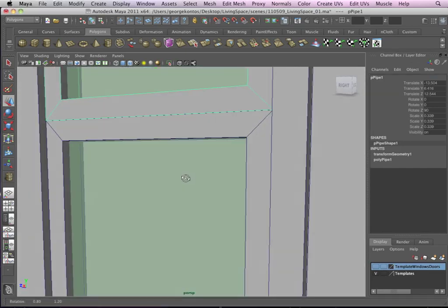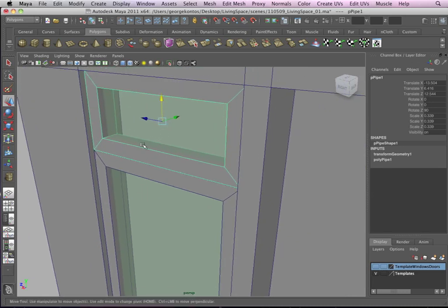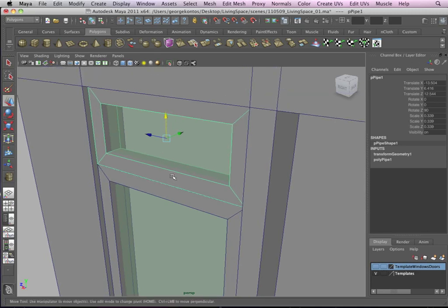So I'm going to select this small frame, and see that a lot of times a CG object has very sharp edges. In reality, nothing has sharp edges. It's not like a razor. We would be cutting our hand all the time if we were walking in the CG model and everything was so sharp, it would be very dangerous. So it's unrealistic, basically. That's what I'm trying to say. In reality, even your Mac screen has a little bit of a bevel. Everything has a little bit of a bevel. Even the ones that look really sharp, there's a beveling between the surfaces, when we change from this surface to the next. So we need to put that into the model here.